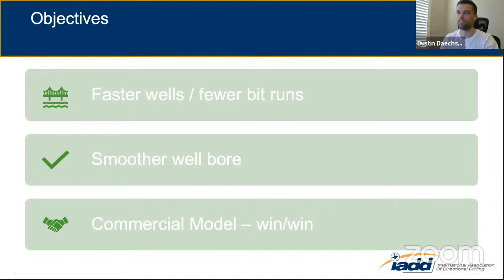Certainly with the big improvements in thermal stability of cutters over the last few years, we've been able to make some pretty large incremental improvements in input horsepower. I would say overall right now, probably the motor is a couple steps above what the drill bit can put out in terms of bit torque. So that continues to evolve.